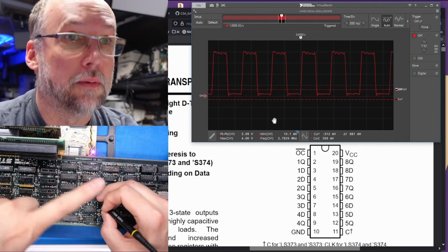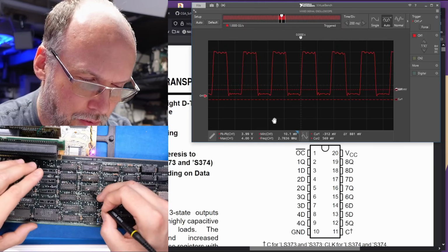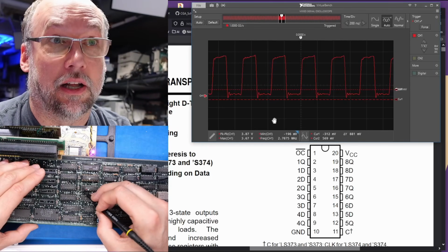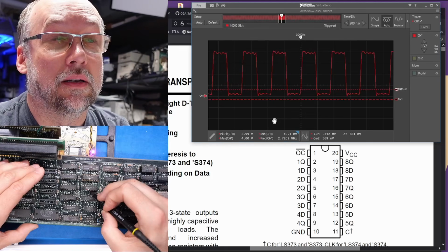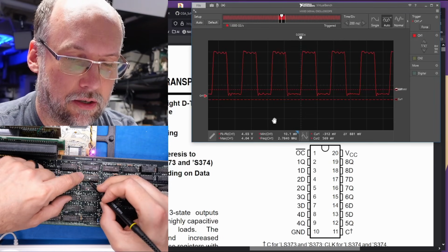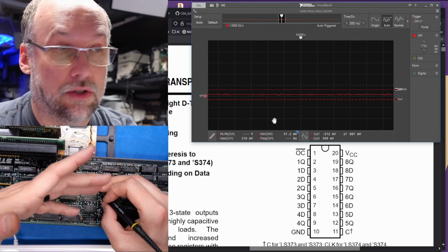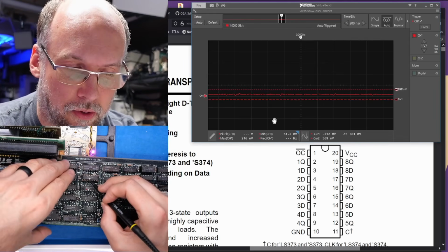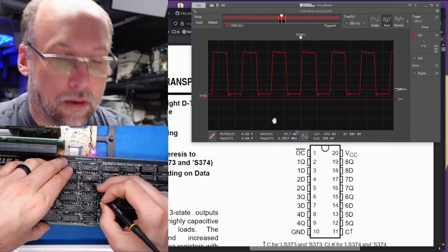All right, so the signal on the mux that we suspect might be having a problem, the output, is that, which looks to be exactly the same as the clock signal. It's basically identical. And that's making its way over here to this mux here, which the output is just ground, right? And we know that's causing the attribute problem based on the input here.